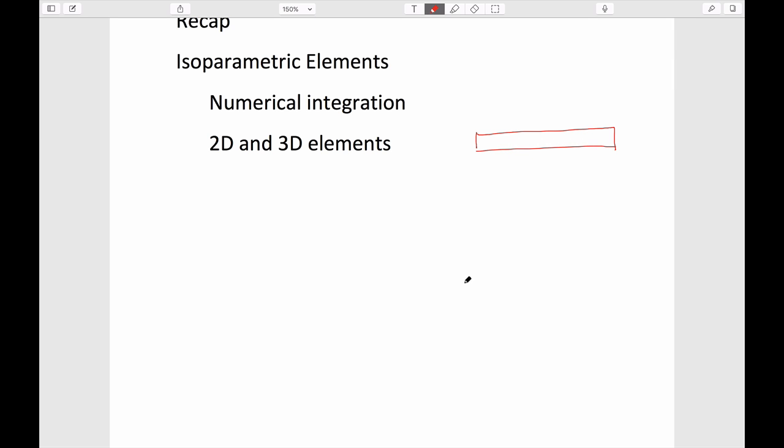And the elements we talked about already was an element that looked like maybe this. So in 2 dimensions, the element looked like this. But instead of just having nodes only at the vertices, it had some mid-side nodes and also in one case had some central nodes, with the whole idea of being able to have a larger density of nodes to be able to pick up these high gradients of head. So the analog for our particular case would be that we have an element that would, for instance, have a central node in it.